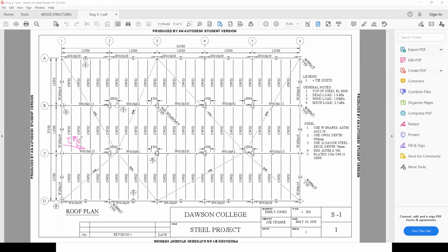So what you do is, for example, let's say I want to put a roof drain right there. I'm going to put a roof drain right there. Therefore, I would have to take the furthest distance away from that drain. It's either going to be this one here or that one there, whichever. I take the furthest distance, and then I multiply it by 0.02. That means that all the steel around that drain has to be that much lower so that I can create that slope.